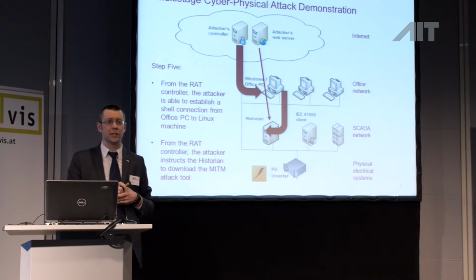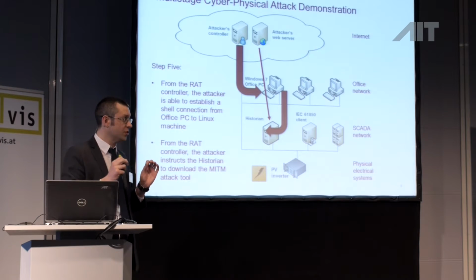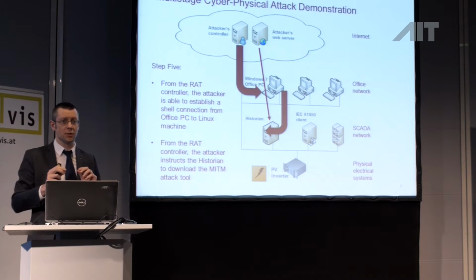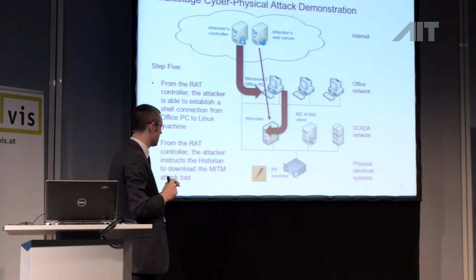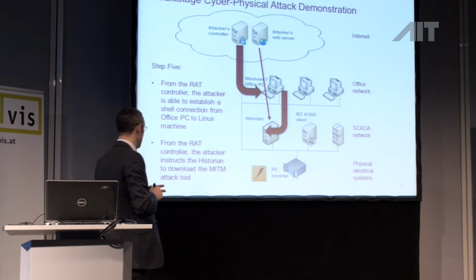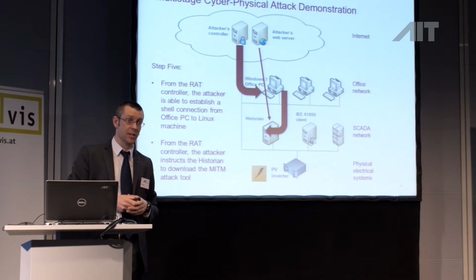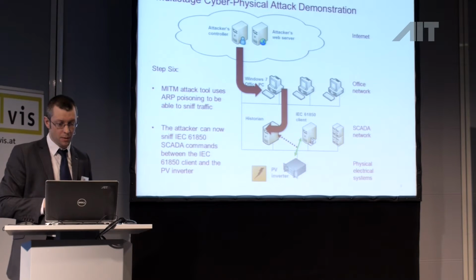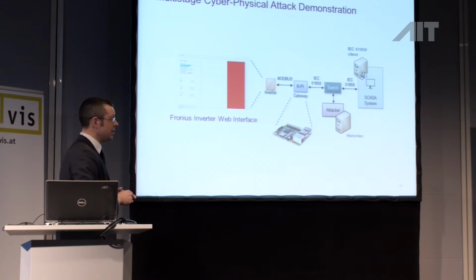This man-in-the-middle attack basically allows us to sniff, or listen to, the normal traffic that's going between the 61850 client and the PV inverter, see that, change it, and then replay it as we see fit. Yes. So this is the final setup.